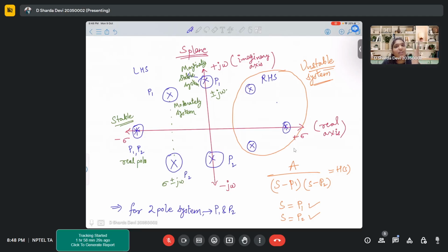But suppose you say, I'm not using that last face, I'm terminating it immediately over there with, let's say, an insulator and designing another MOSFET beyond that. In that particular case, you will not consider that 5th face. But majority of the times, if it is a single MOSFET, you don't need that division, so you will have that 5th face. So that's why in the calculations that we have done, we have considered all 5 faces. Are you getting my point?